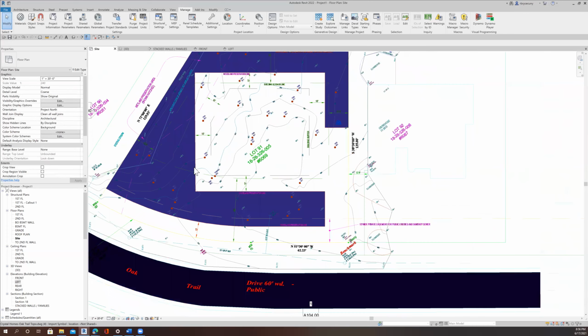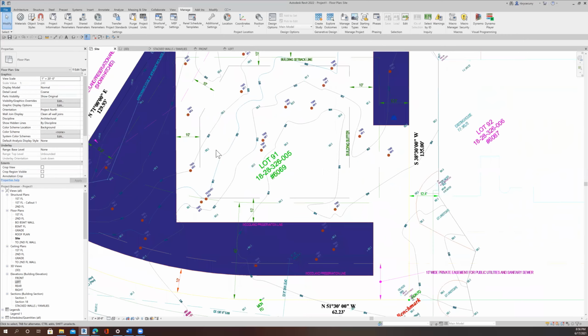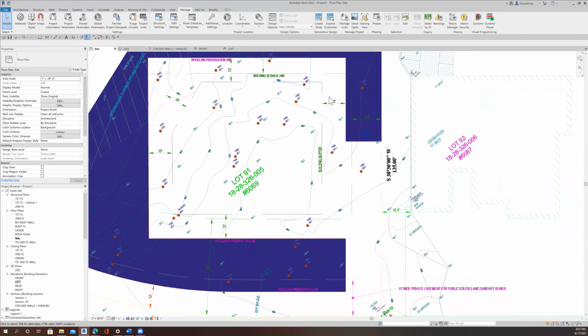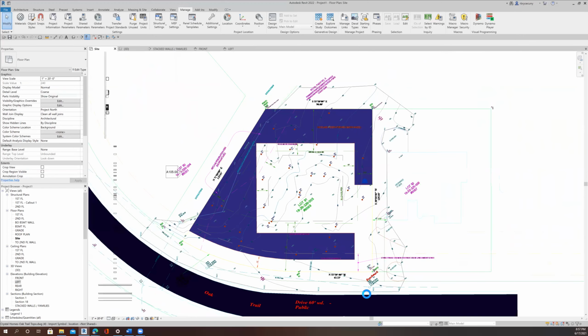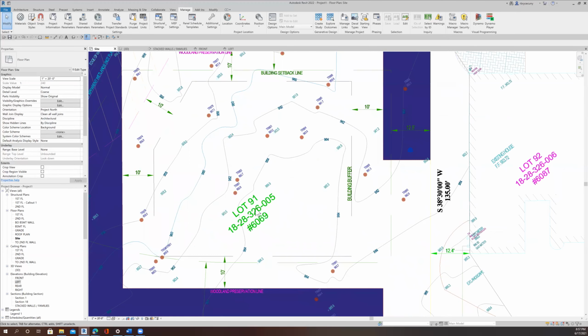So what they've said is, here's the preservation area legally defined, but still we have put another restriction, which means we have to be another 10 feet off of those boundaries. So the surveyor was nice enough to create that for me. So I know I have my building envelope right here. And that changes over here, because this would be assumed that that's where the driveway is going to come in for the garage.